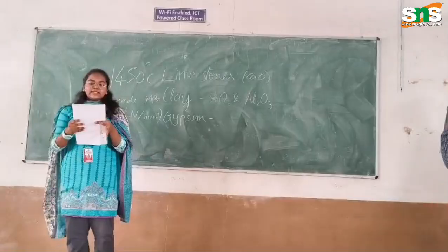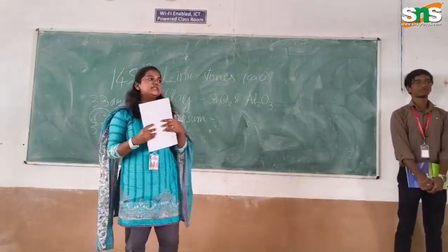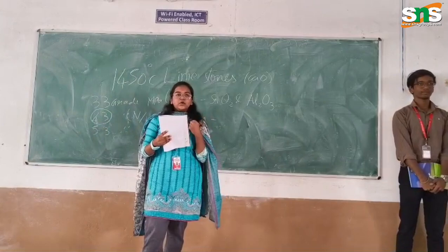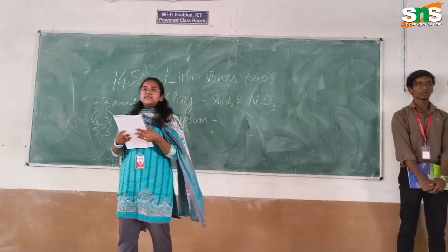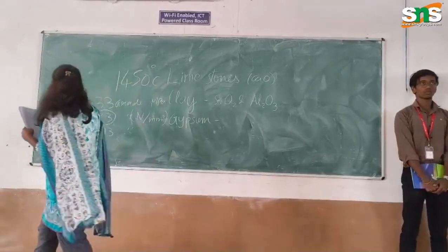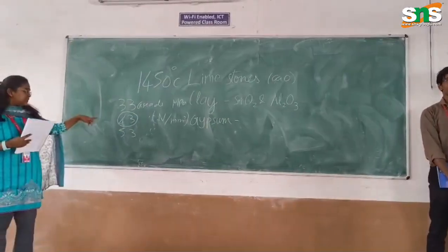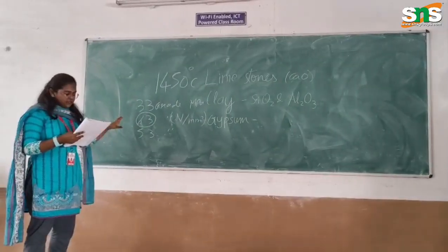Two main strengths, that is compressive strength and tensile strength. Compressive strength is how much load or weight or pressure a cement can withstand, that is when it is pressed or squeezed. Cement grades like 43, 33 and 53 are classified based on the compressive strength.